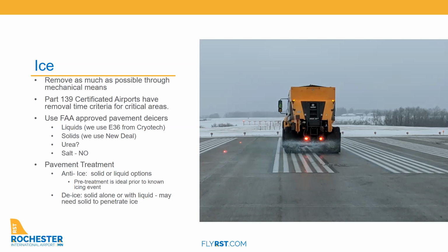On the other side of it, I've had situations where we thought we were going to get freezing rain. We applied liquid on the runway, so it makes the runway essentially wet. And then instead of ice, we got snow. Well, now instead of that snow blowing across, it's sticking to that chemical. Created a problem,